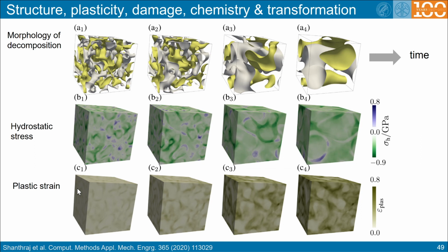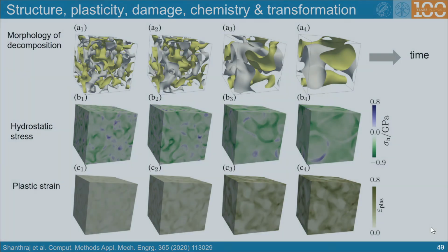And that is done in a recent implementation in DAMASK, where we combine plasticity, phase transformation, diffusion, and Ostwald ripening. This is realized in the underlying models by combining crystal plasticity with phase field and with Allen-Cahn type of simulations.